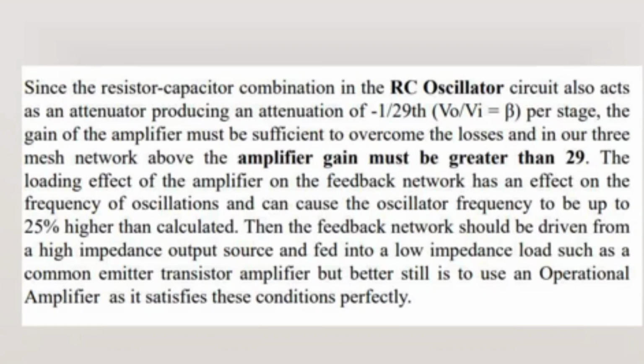Then the feedback network should be driven from a high impedance output source and fed into a low impedance load such as a common emitter transistor amplifier, but better still is to use an operational amplifier as it satisfies these conditions perfectly.